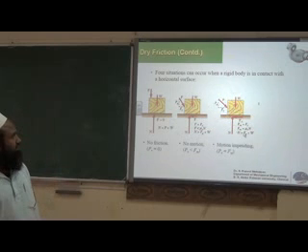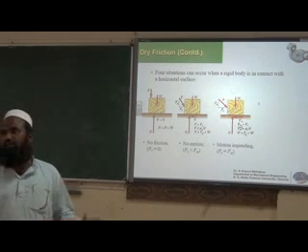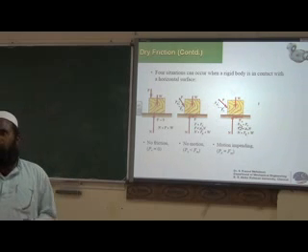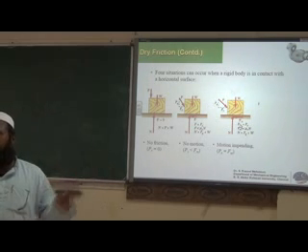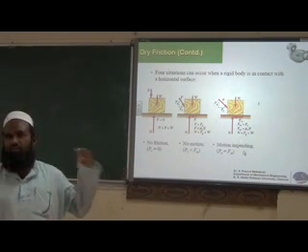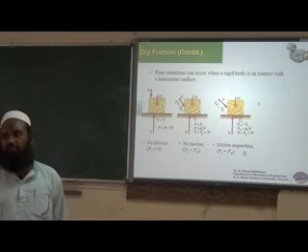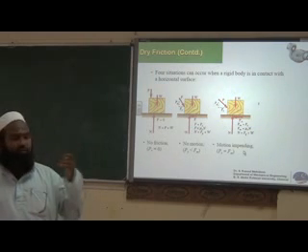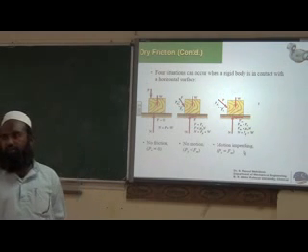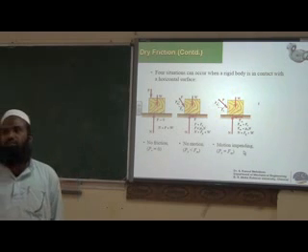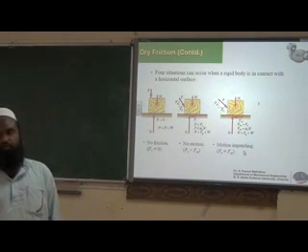Here, both are equal. The horizontal component is equivalent to the maximum frictional force, so motion begins. Impending refers to the beginning of the motion. Generally we use the words "motion impending." Motion starts, motion begins here. So here the maximum frictional force Fm will be equal to the horizontal force which is applied to move the block.